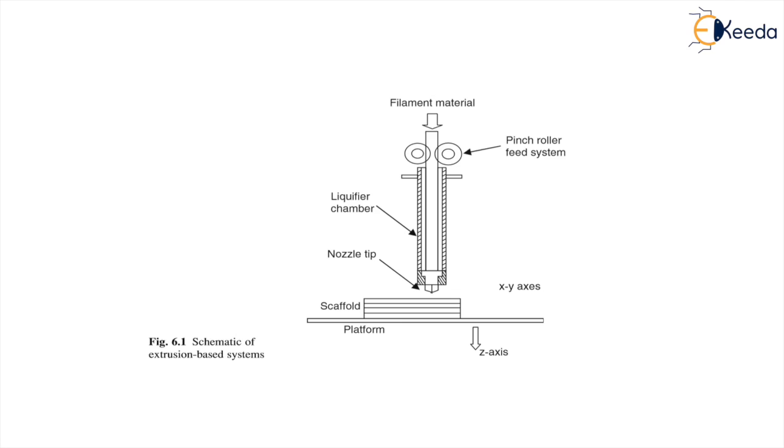So it is like an extrusion process: loading of the material, liquefaction of the material, application of pressure to move the material through the nozzle, then the extrusion process, then plotting according to the predefined path in a controlled manner, then bonding of material to itself or a secondary build material to form a coherent solid structure, and the inclusion of support structure to enable complex geometrical features.